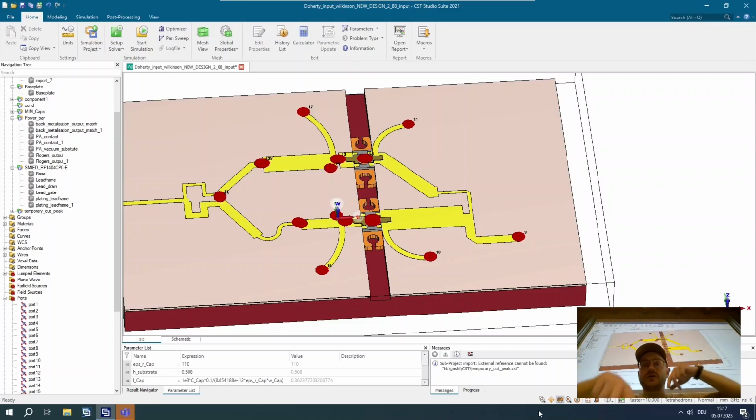which with a microstrip line you will not be able to achieve, because the impedances that you see on a microstrip line are not only dependent on the width of the line, but also on the height of the substrate. But the benefit of the microstrip line is that it is one carrier which you can meander around. And the coplanar wave is basically a three carrier medium, which meandering around is very difficult.